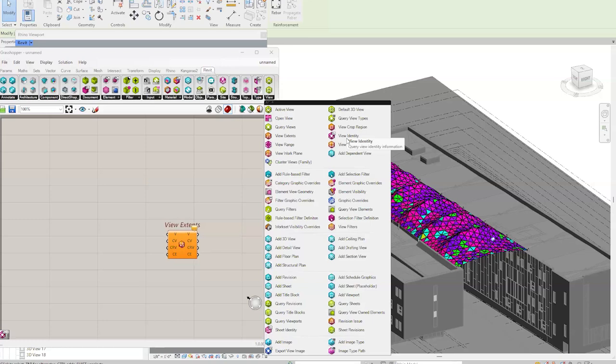I'll check to make sure that we have a feature request, because that is a really good one and a really big pain. Granted, a lot of people use scope boxes to manage that. But we're always going to be limited by the Revit API. When David was showing how he added a wall, the Revit API lets you create a wall two ways: you can do a line, picking two points, or you can do a wall by profile.